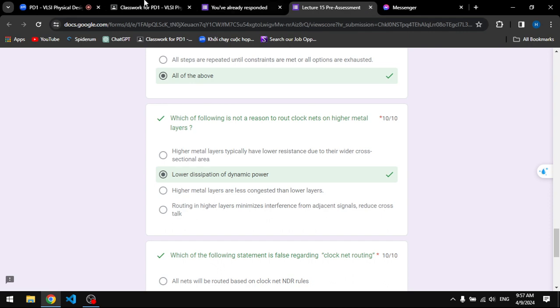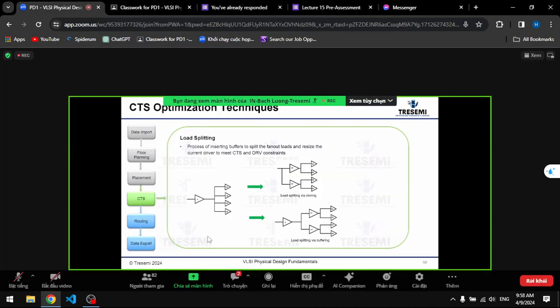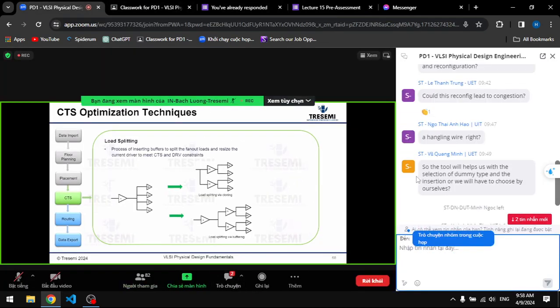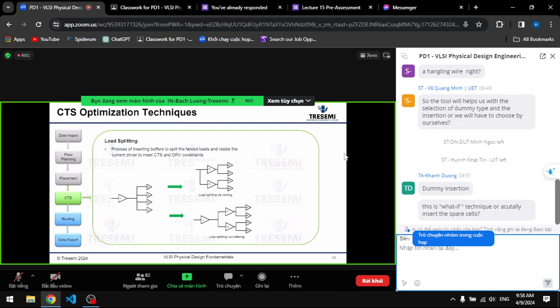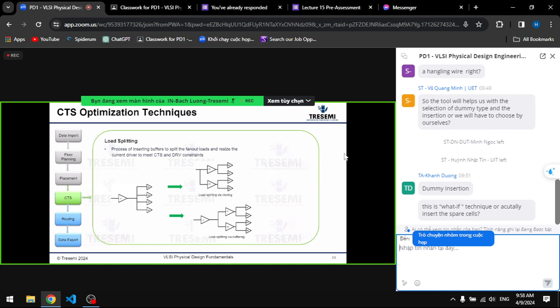When you are about to tape out, meaning you are almost done, you want to minimize changes as much as possible because your timings are in place. It's like a doctor doing surgery on your chip: you change only a little bit to fix what you need and do not let the tool touch it.